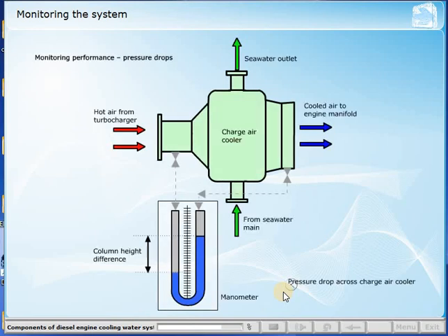When a heat exchanger is partly blocked, then the fluid flow is reduced, and this will affect the system temperatures as well as the pressures. Considering a jacket water cooler with seawater as the coolant, the seawater side is the most likely to get blocked due to shells and other marine debris. If a partial blockage occurs, it can be indicated in two ways.